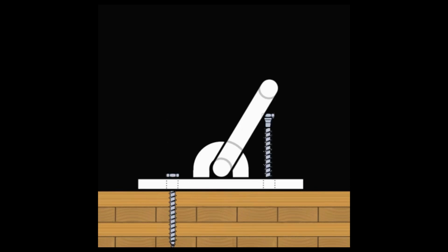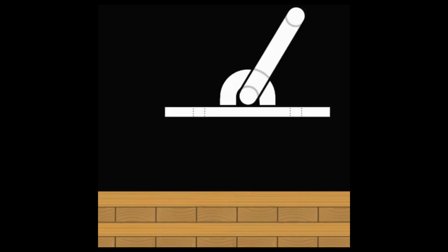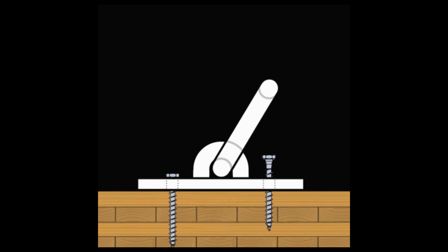Let's just see it more visually. You just place your yoke anchors respecting your edge distances on the panel you want to lift. You screw them in using self-tapping screws. Then you would place your sling and do your lifting. And removing the hardware is just as easy. You just simply remove your self-tapping screws, and as my French colleague would say, voila, you're done.